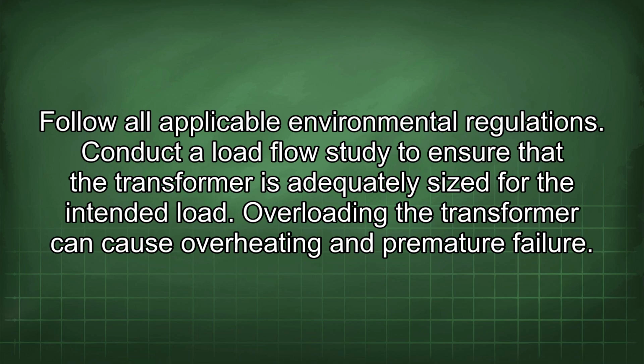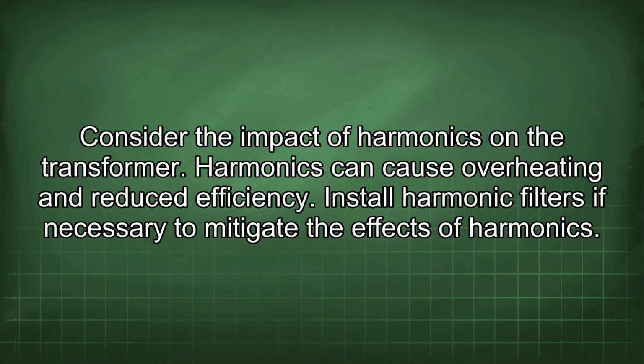Conduct a load flow study to ensure that the transformer is adequately sized for the intended load. Overloading the transformer can cause overheating and premature failure. Consider the impact of harmonics on the transformer. Harmonics can cause overheating and reduced efficiency. Install harmonic filters if necessary to mitigate the effects of harmonics.